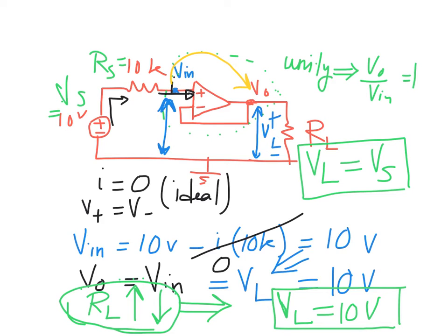What are the benefits behind this? We translated the voltage without any distortion, without any losses in resistance or any other parts of the circuit. And the most beneficial part, it won't depend on the value of RL. So you can change the load in any way. At the end, the load voltage will remain the same as at the input of this point here, as what happened previously.